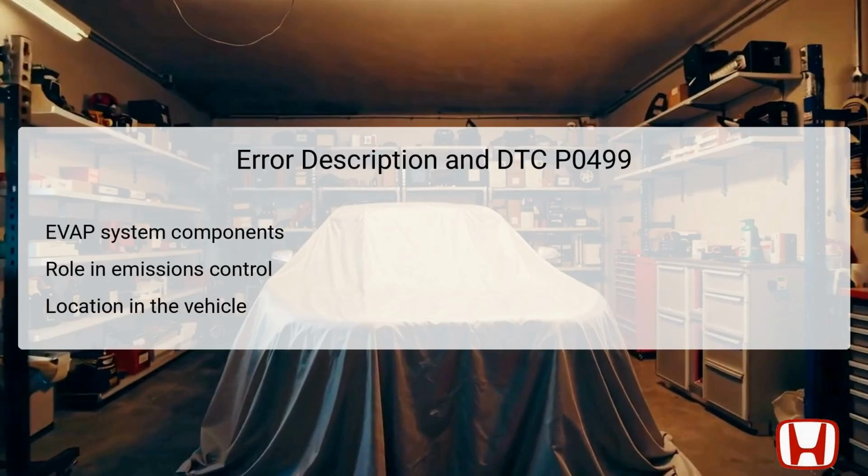The EVAP canister vent shut valve is an integral component of the EVAP system, which includes several parts such as hoses, valves, and the ECM, engine control module. The role of the vent shut valve is to prevent fuel vapors from escaping into the atmosphere by shutting off the vent when certain conditions are met, thereby aiding in emissions control. This prevents harmful vapors from being released, contributing to cleaner air. The valve is usually located in the vicinity of the fuel tank, part of the broader EVAP canister structure.